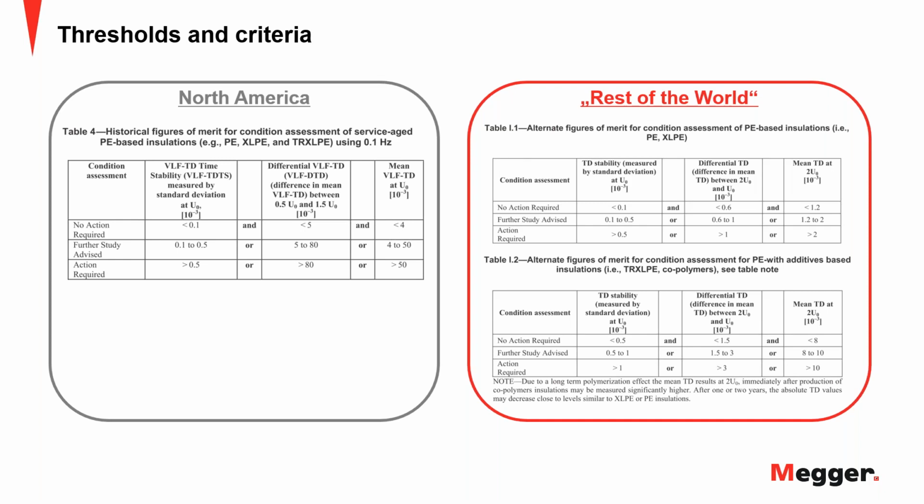But you can certainly have different leakage current amongst three phases. That is not something out of the ordinary. Even when you do tan delta testing, you can have one phase that tests very well and two phases maybe that test not so good.